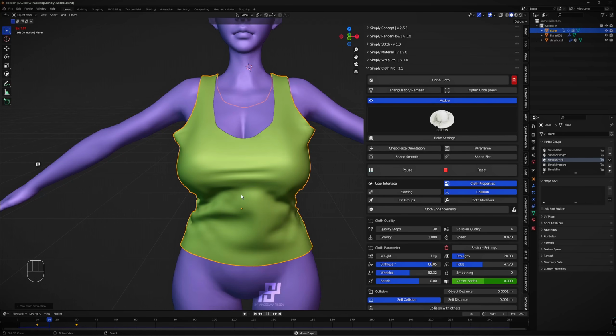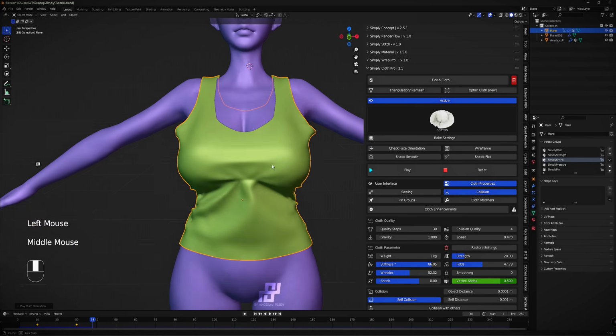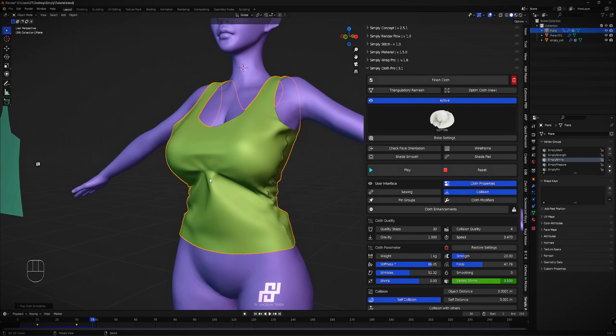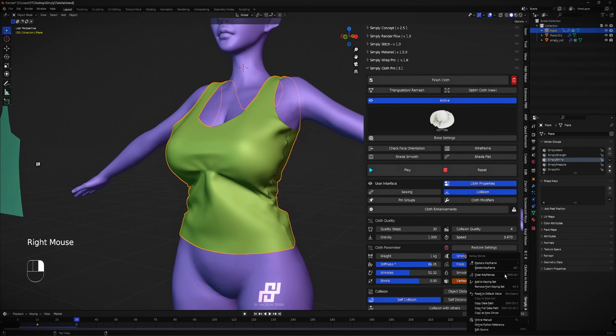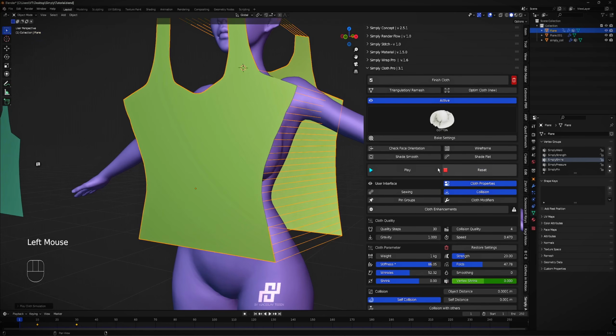So notice here, slowly, then it is shrinking. In our case here, it's not that much shrinking. We have 0.5. We can go to the timeline and check here in frame 30. You can adjust it to a higher value and replace the keyframe.